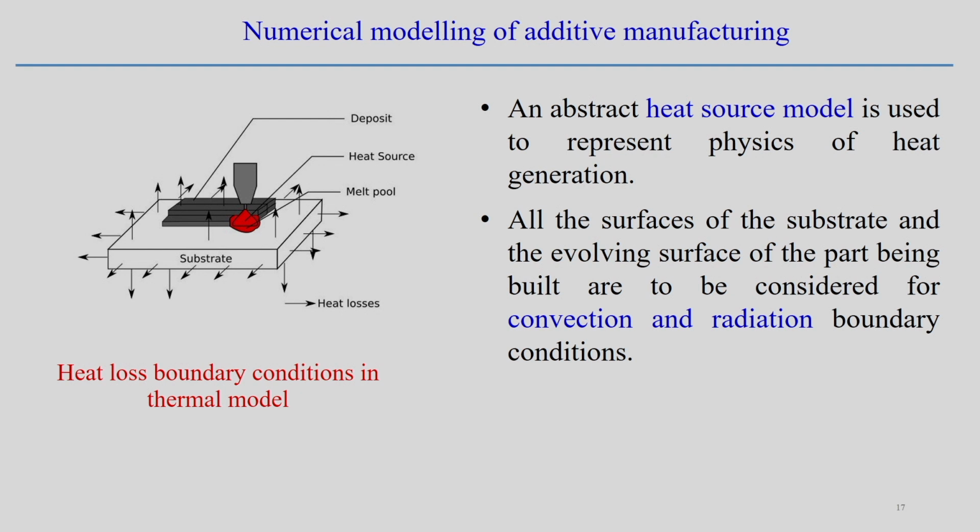The other thing is, if you see this as a control volume, the heat source is applied, that is, the laser source is interacting over the boundary. That can be implemented in the form of a boundary interaction, but if you develop the volumetric heat source model, then that heat source model is incorporated in the governing equation only. In that case you can neglect the surface flux which interacts through the boundary by the laser or the arc, which may not be considered in this particular case.